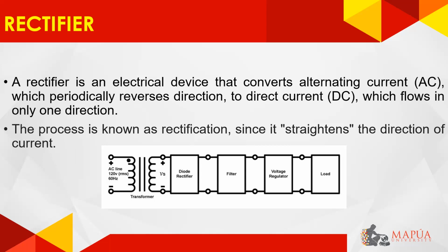So what is a bridge type rectifier? The rectifier efficiency of a bridge rectifier is almost equal to the center tap full wave rectifier. The only advantage of bridge rectifier over center tap full wave rectifier is the reduction in cost. In addition, in bridge rectifier, instead of using the center tap transformer, 4 diodes are used.